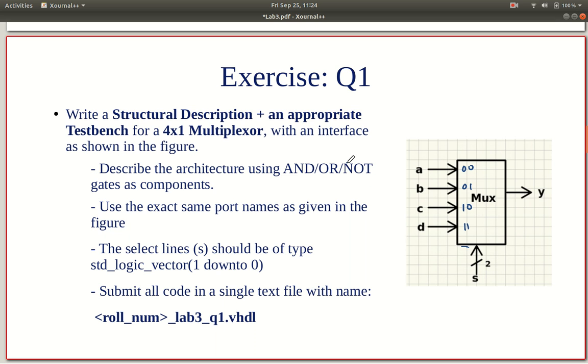You are asked to model this using VHDL using a structural description. That means describe it as an interconnection of simpler and, or, and not components. So describe these and, or, not entities. Derive the logic expression and a simple circuit diagram for this, and build this mux.